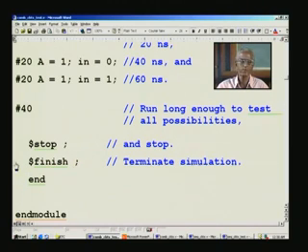If you do not give this also, it does not really matter. And finally we started with initial, then begin, and a matching end is this, and we also started a module, so there must be an end module. So, this completes the test bench for the most primitive design, just a 2 input AND gate. Are you clear about this? Then with this background we can go to the next.